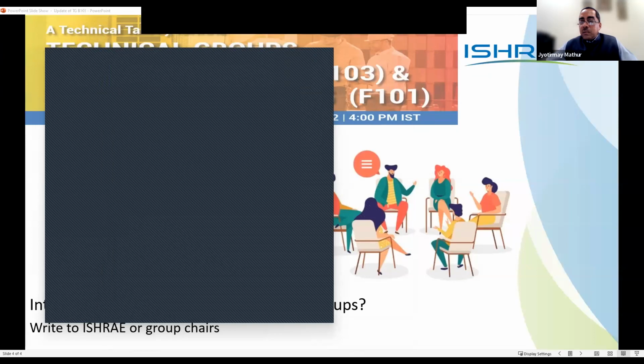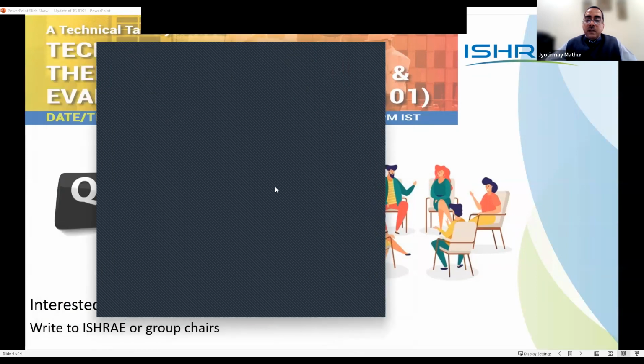First of all, on thermal comfort, there is one question. Is type of building, ventilation rate, and heat gain of building not part of thermal comfort basics, as discussed in the earlier slide? I think the reference is to the slide on which basic parameters like temperature, humidity, air velocity, MRT, clothing were shown. So I think the slide was referring to the parameters, and ventilation rate and heat gain, these are influencers on these parameters.